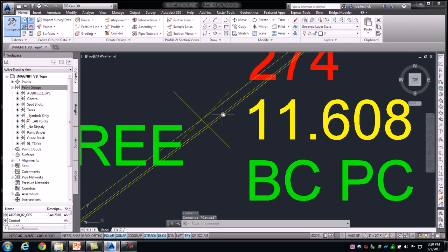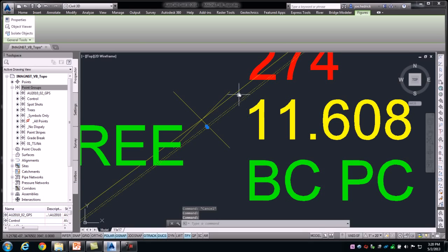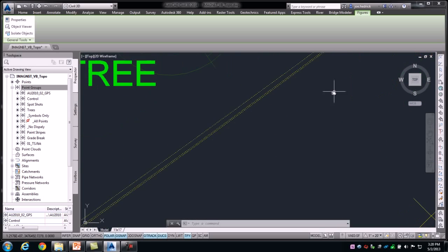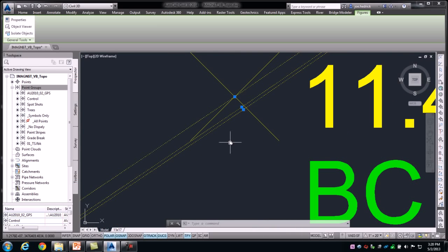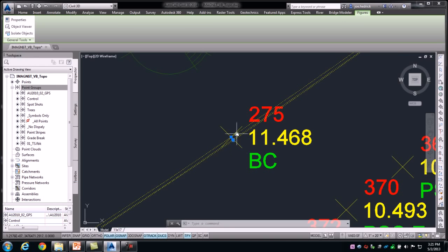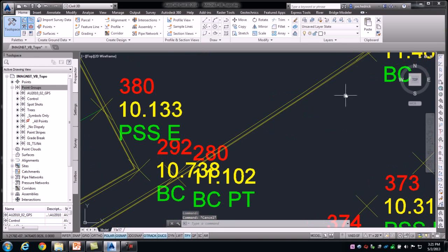You'll even see if I highlight these particular figures, we do have grips at those points. I never physically shot this. However, Civil 3D is connecting that linework for me as well. Right, this works great if you're doing as-built collection. Maybe the curb was put down with a curb machine. It's very uniform. It doesn't change. It's always going to be that half a foot over, half a foot down type of scenario. And we can really reduce the amount of shots that we have to take there.